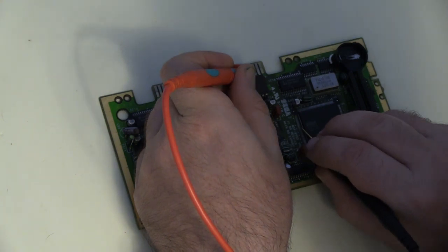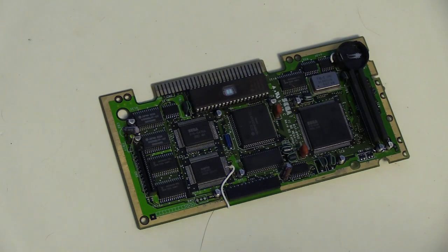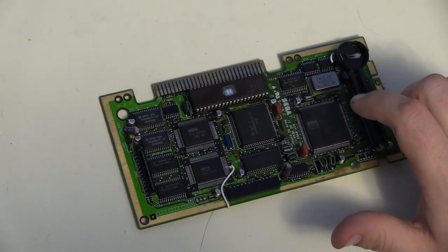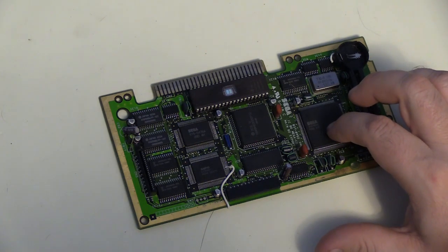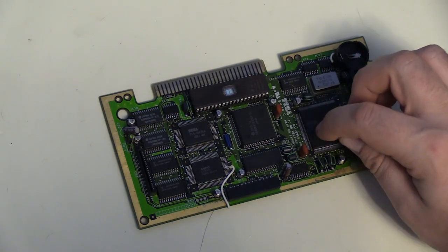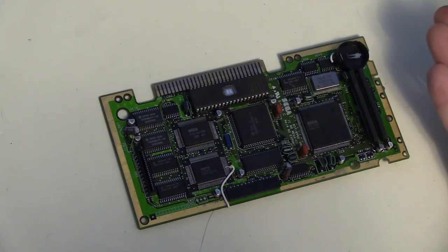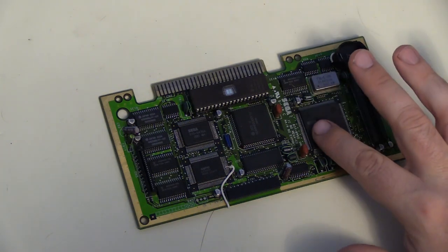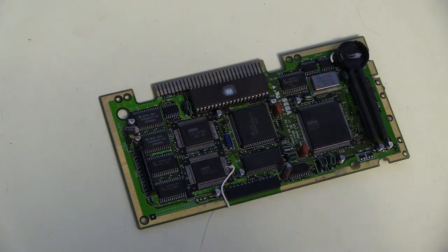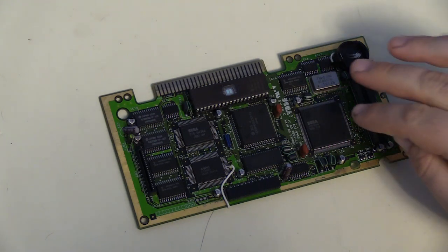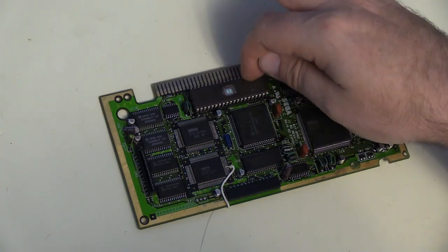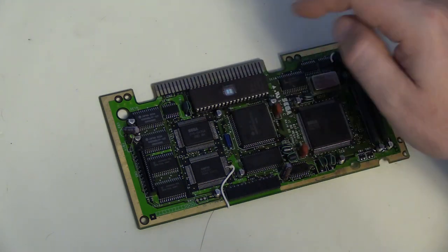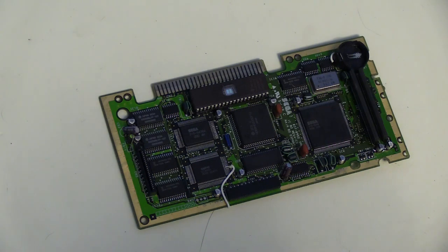So what's happening then is that there's been a failure inside this custom Sega CD processing engine where it is holding several of those address lines high from when the system is first powered on. Normally those lines are supposed to be low so the Genesis can do its communication without interference. But when this is forcing these lines to be held high, it's causing the Genesis to set addresses wrong, and then it's reading garbage code out.